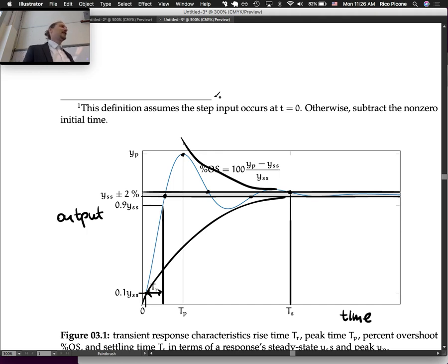It's underdamped, it has a couple oscillations, so it's not 0.8 or 0.9 damping, it's lower than that, it could be 0.5 to 0.2. And then the natural frequency, you could approximate by looking at the oscillation peaks here. It's not perfect, but it's one way to estimate it. Look at the difference in time and take 2 pi and divide it by that time, and you'd have approximately the natural frequency. Does that make sense? Okay.